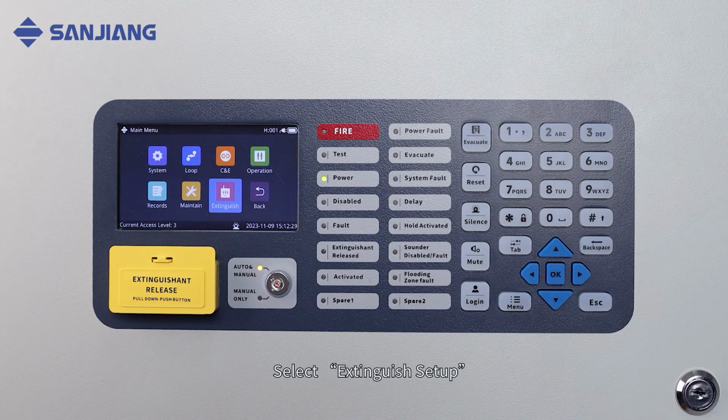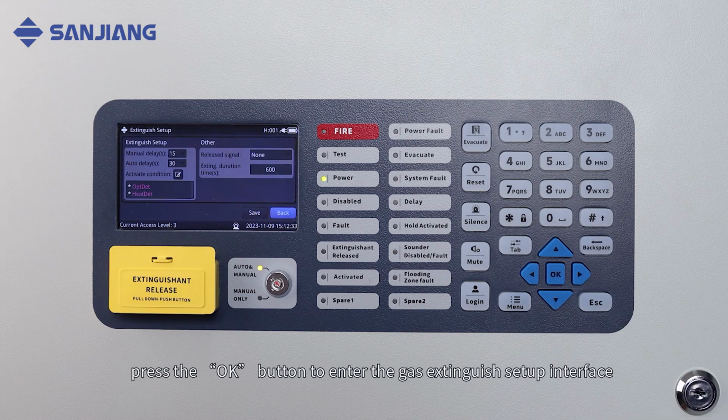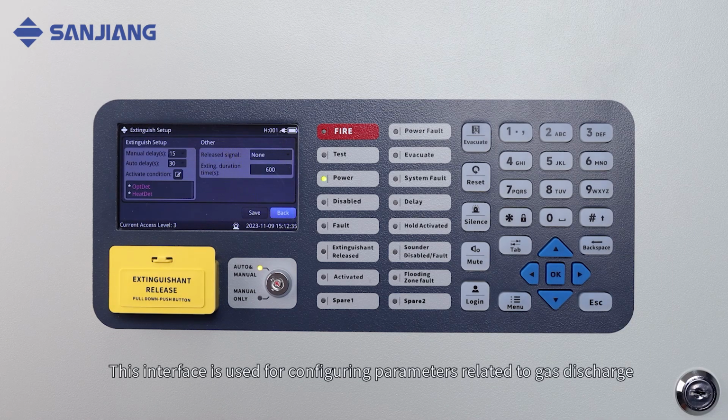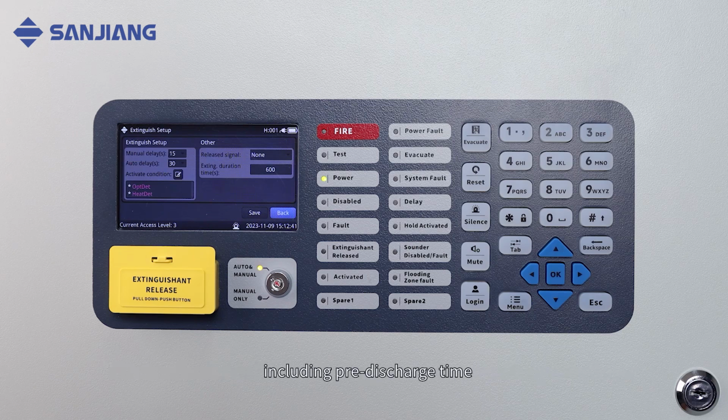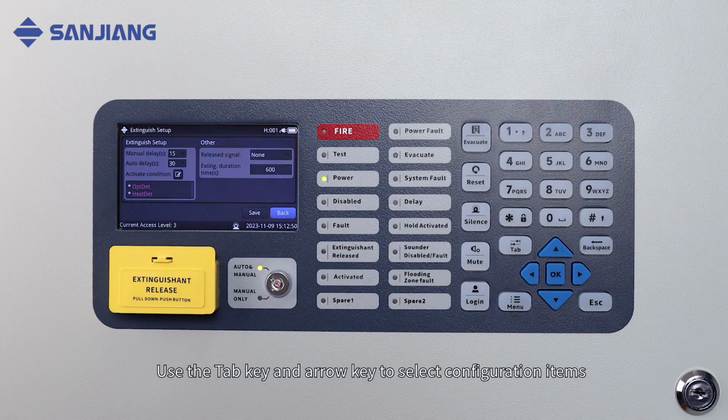Select Extinguish Setup. Press the OK button to enter the Gas Extinguish Setup interface. This interface is used for configuring parameters related to gas discharge, including pre-discharge time, solenoid valve drive time, and automatic discharge conditions. Use the Tab key and arrow key to select configuration items.